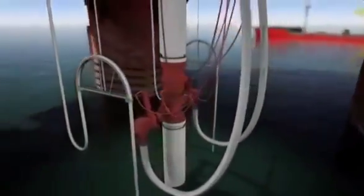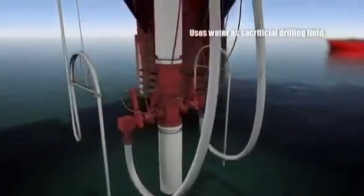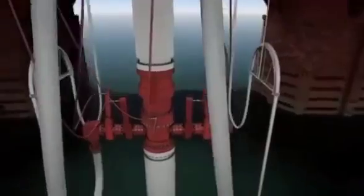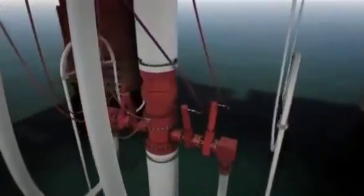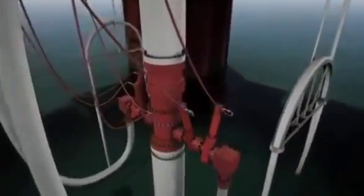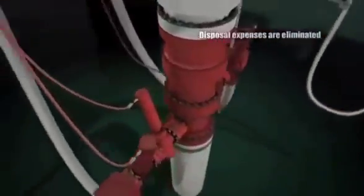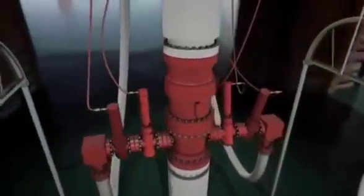Costs are also reduced by using water as a sacrificial drilling fluid, instead of pumping expensive fluid systems and lost circulation materials into the formation. In addition, disposal expenses are eliminated because cuttings are injected into the formation along with the drilling fluid.